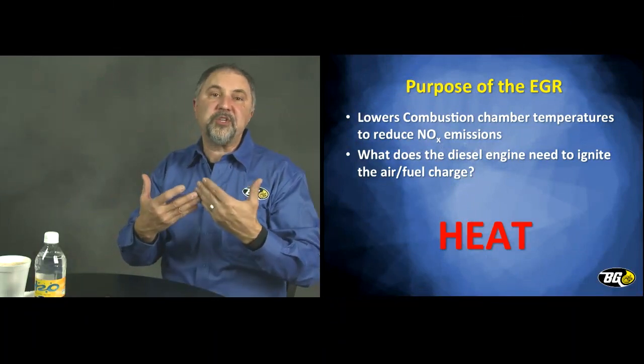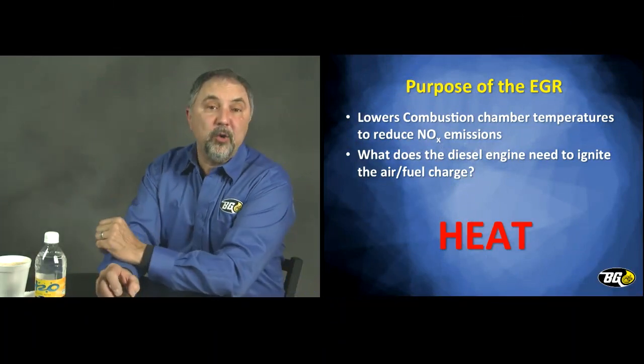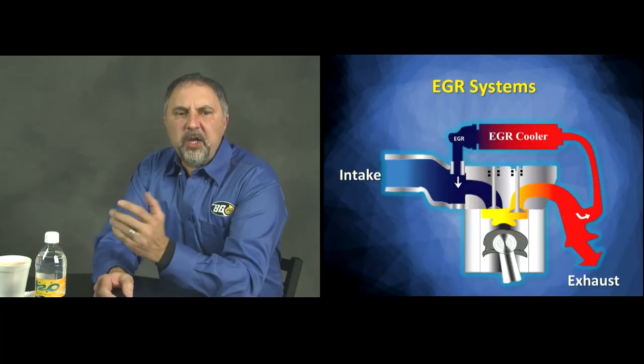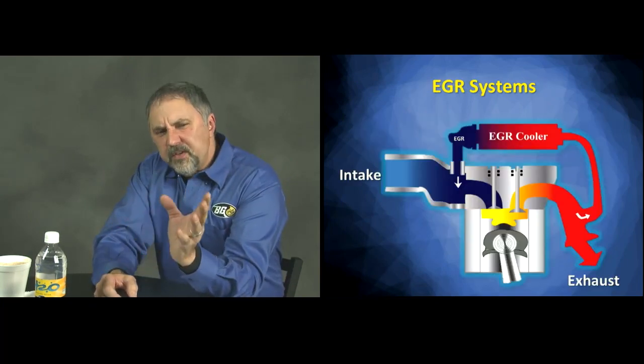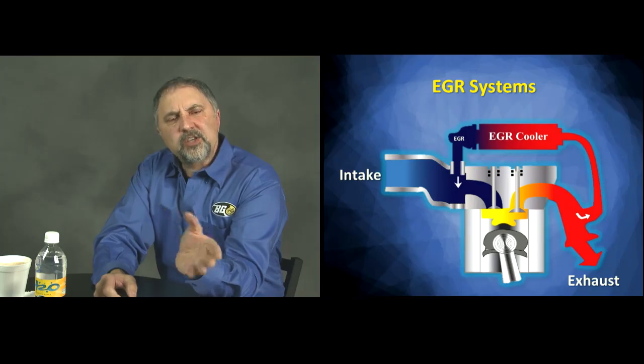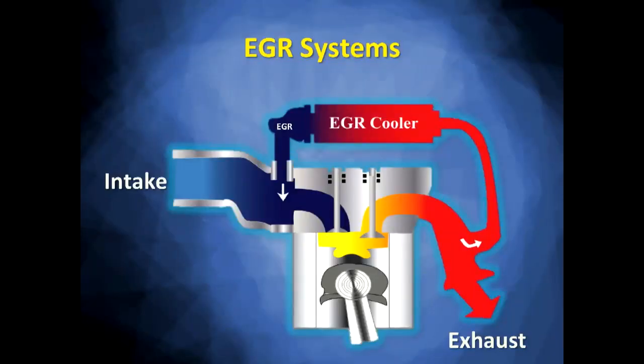And we're here to get these engines restored back to like new conditions so they run at peak performance. Now, the EGR valve itself, if you can see the same type of schematic, and you'll notice on the exhaust valve it's slightly open, that's in the yellow. And as exhaust gases escape through the cylinder and are pushed out through the tailpipe, some of those exhaust gases will be recirculated back up through the EGR and the EGR coolers and be recirculated down into the intake manifold.